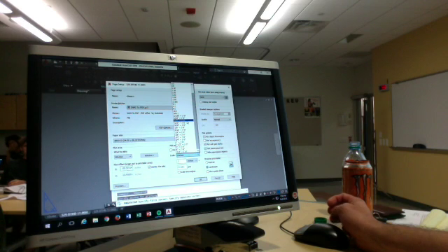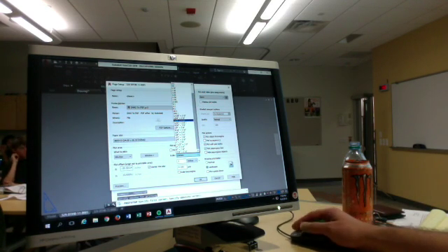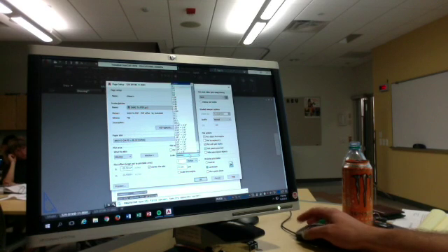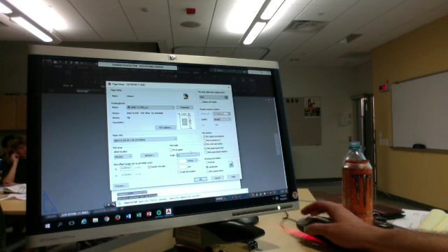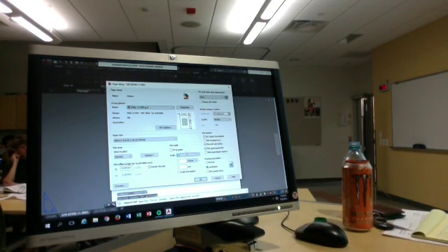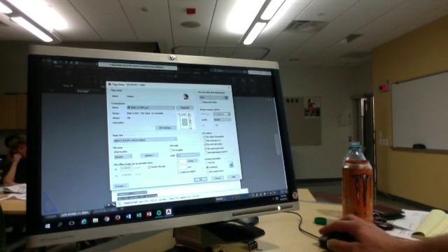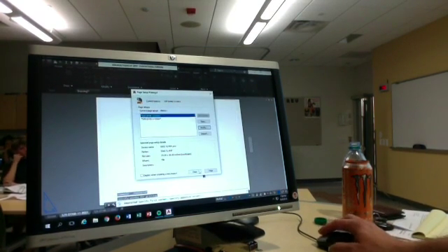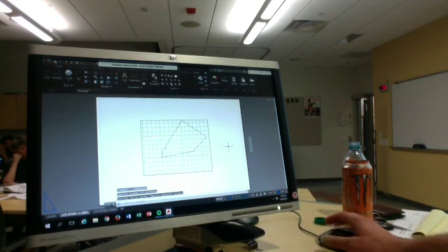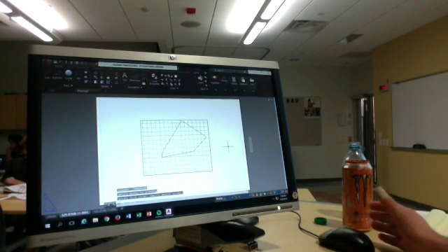What's cool is that when you print something to scale and use an architectural ruler and you measure it, it's spot on. I do it all the time at work. It's pretty convenient. So this one, let's see here, 1 to 1. No, we'll go up to 1. No, we want 2 to 1. So yeah, 2 to 1 puts it nicely on the paper. We will be talking more about this type of stuff later. But hit OK, and you hit close. And it nicely puts it on the 24 by 36 piece of paper.